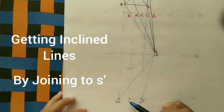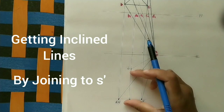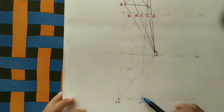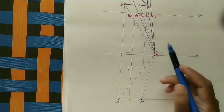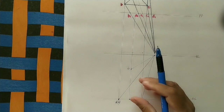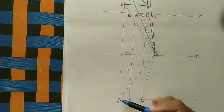Join all these A, B, C, D and apex points to H dash with the help of a scale, getting inclined lines. After getting these points, on the ground line we have marked the apex also. This height is 6 centimeters we took. After that, if we join all these points, we will get the side view of the pyramid. Now our main aim is to do the perspective view. Initially we will do the perspective view, after that we will do the side view by joining this.